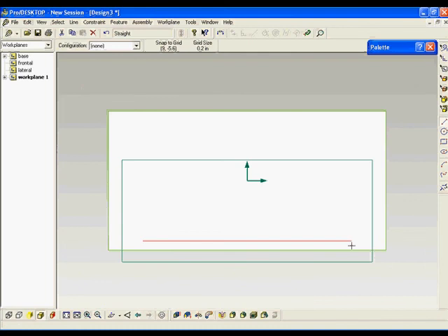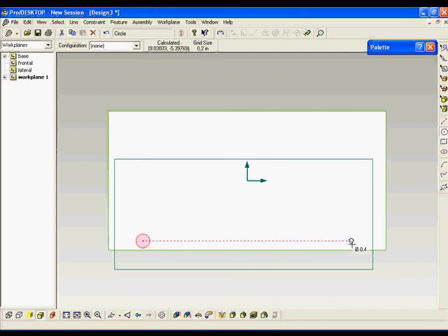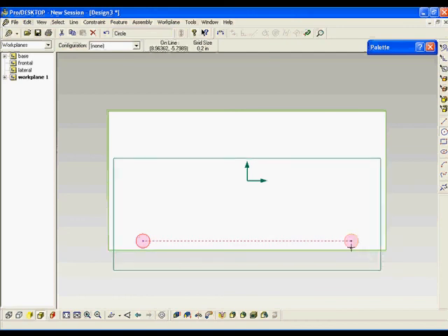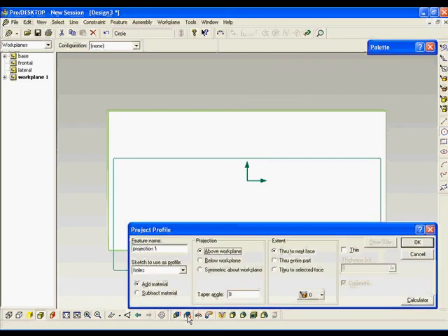Now select Control G on your keyboard, and that makes it a perforated or dotted line. On either end of the dotted line, you're going to put a circle, and the diameter of the circles on either end are going to match the inner circle of the wheel and the axle, which is 1 inch. So I should go up and dimension each one of those circles to ensure that they are 1 inch in diameter. At this point, we're going to go in and drill holes into the van body using the circle as a guide.